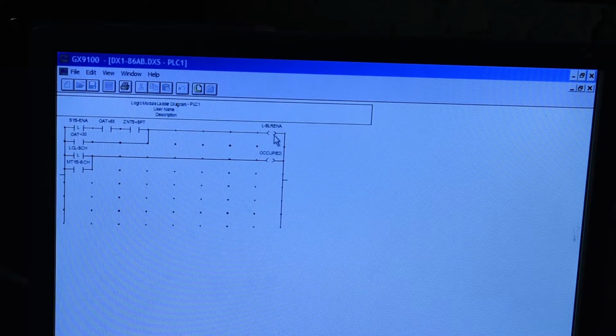This boiler is going to become enabled. Or if the outdoor air temperature drops below, let's say 0 degrees, it's going to force this boiler on. We also have a local schedule that's going to allow it to be in occupied or unoccupied mode.